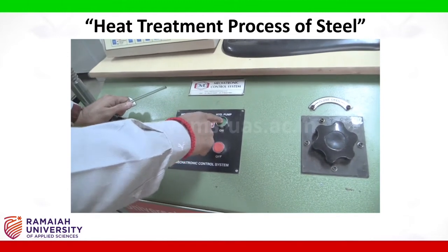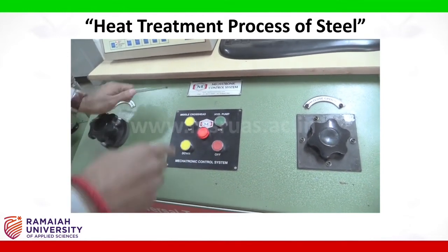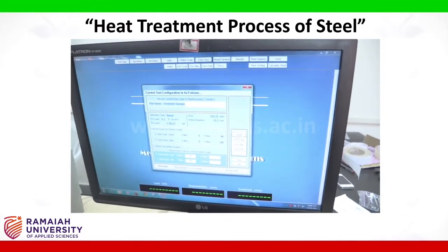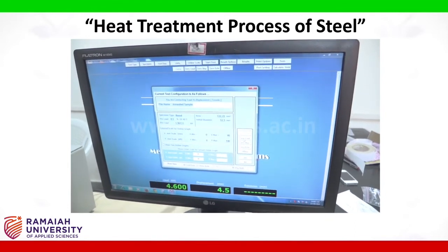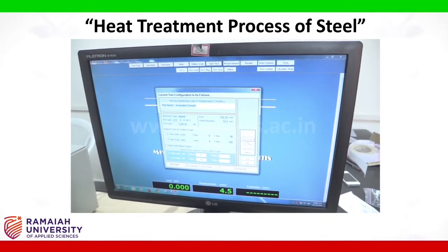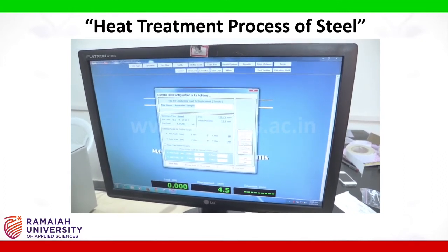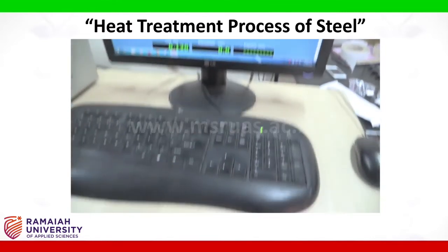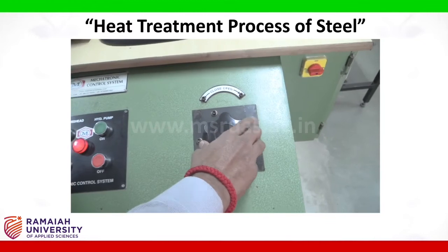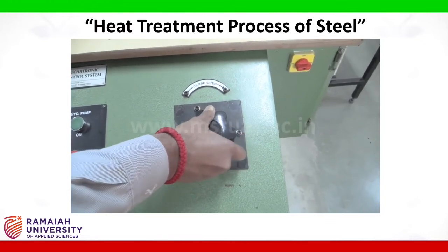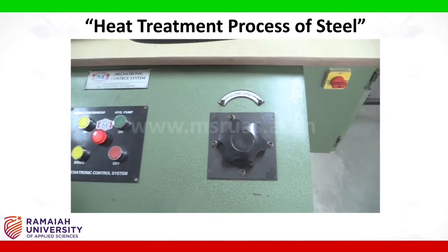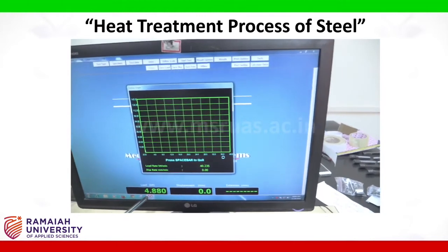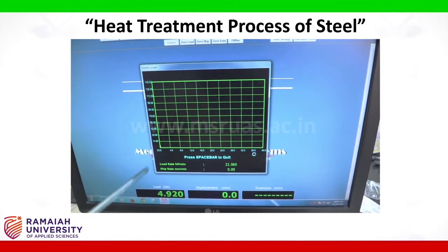Switch on the hydraulic pump and make the scale online and set 0 load and 0 displacement and then say yes. Here the loading is given, a constant load is applied. You can see the load versus displacement graph is generated.